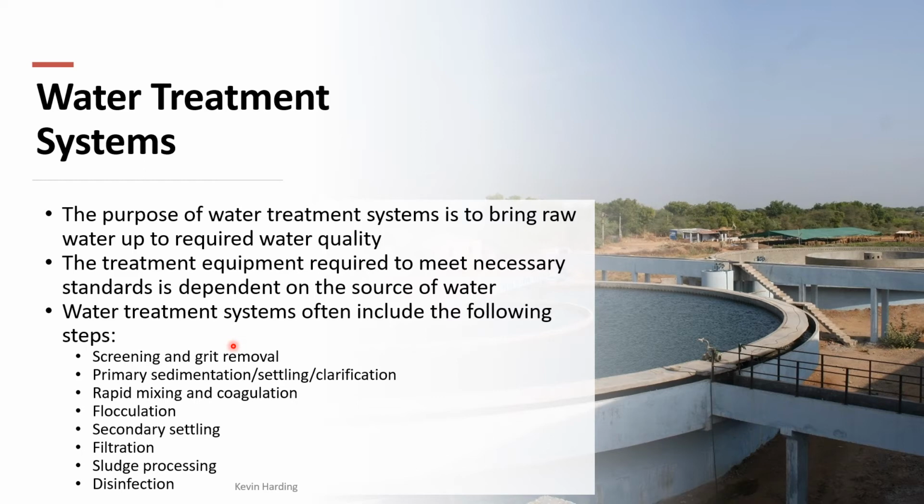The second one is the stormwater drain, and a lot of people get confused and think that the stormwater drain comes to the same system. The stormwater drain is the thing that's in the streets. Anything that you see on the street, there's a little opening in the streets, then the water can flow down when it floods. That system does not go to a wastewater treatment system, it goes straight into our rivers. So when you see people throwing things into the streets and then it gets washed into those systems, it's not ever going to get collected, it's going straight into our rivers. Okay, so those are the two different systems: the stormwater drains, which we are not dealing with today, and the municipal sewage works, which is what we're showing on this slide and from now on.